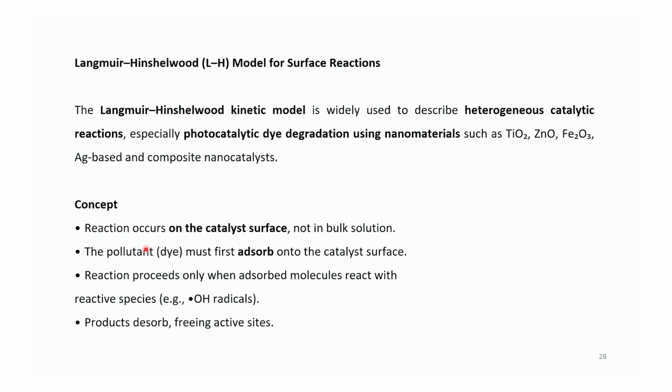So what is the concept? The reaction occurs on the catalyst surface, not in the bulk solution. The pollutant must first adsorb onto the catalyst surface. The reaction proceeds only when the adsorbed molecules react with the reactive species. Then the pollutants desorb, freeing the active sites. So this is what is happening.